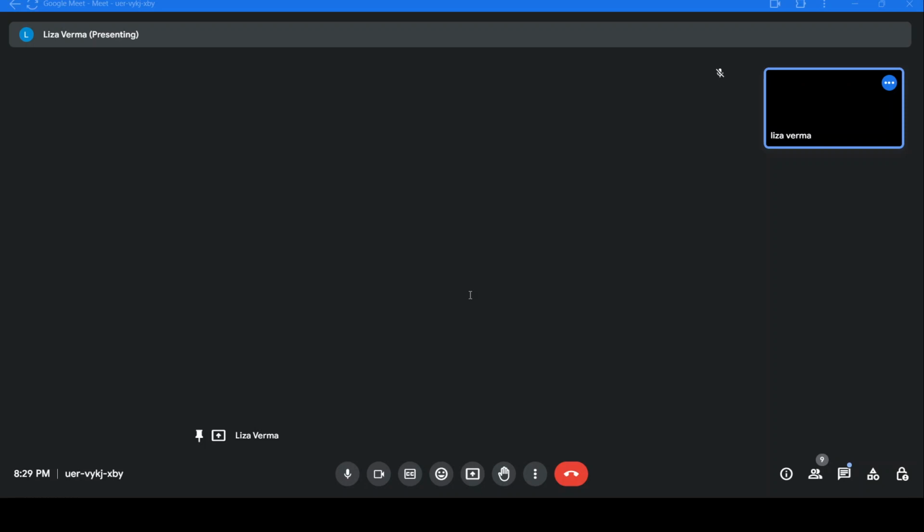No, the RST 0, the 0th location, is nothing but the call vector location for RST 0, the software interrupt, right? Yes. So I think the reset location depends on the manufacturer. So when a reset comes, generally I think it's 0 as far as I can remember.